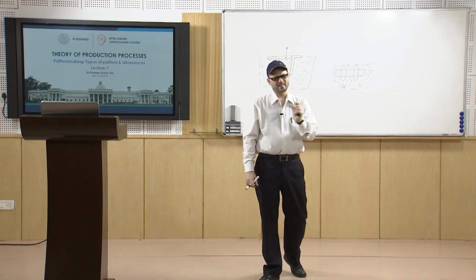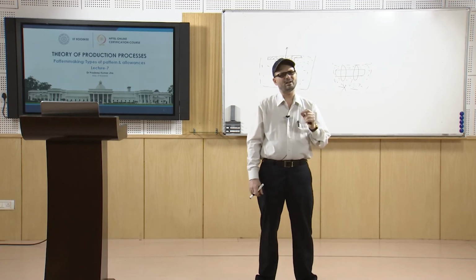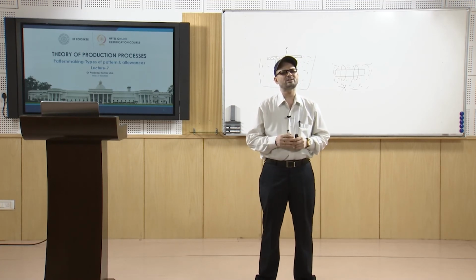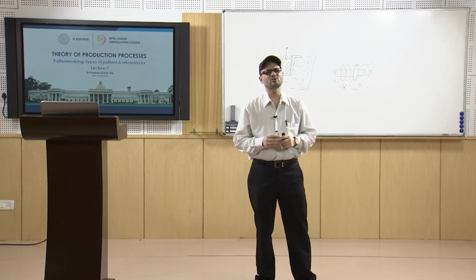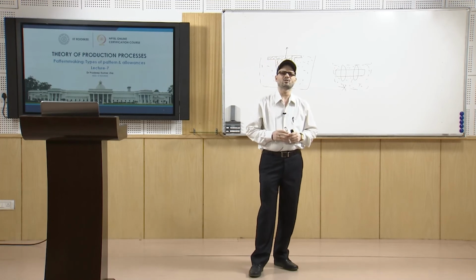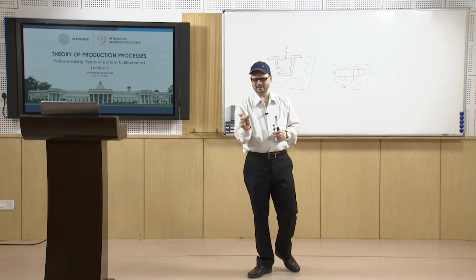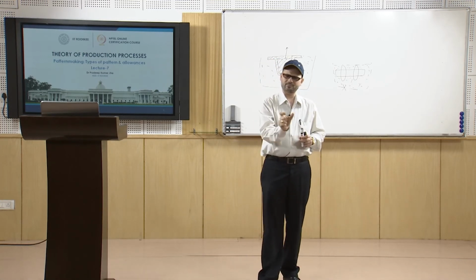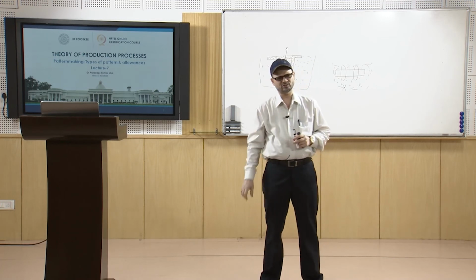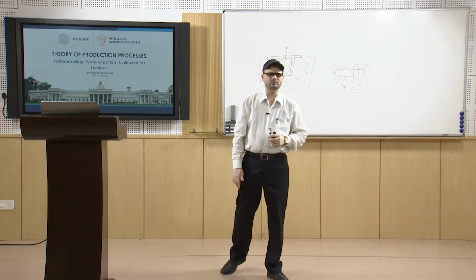So, this is a negative kind of allowance, which is applied only to those dimensions which are parallel to the parting plane, that is width or thickness, and not the height, because the oversizing applies only to the lateral dimensions.